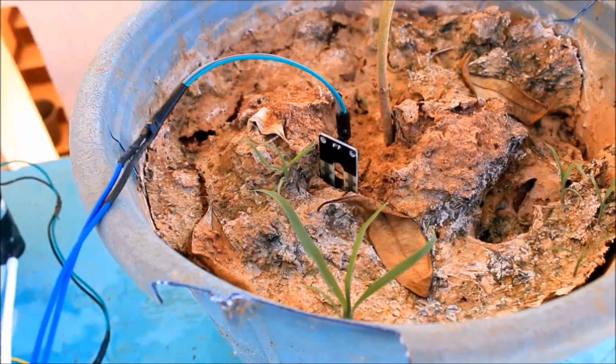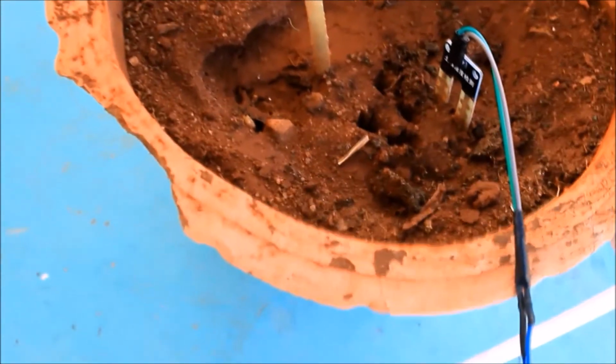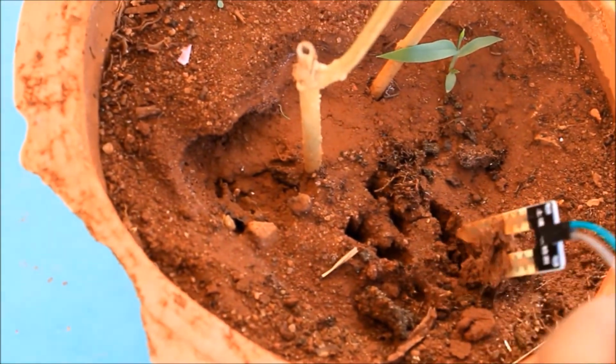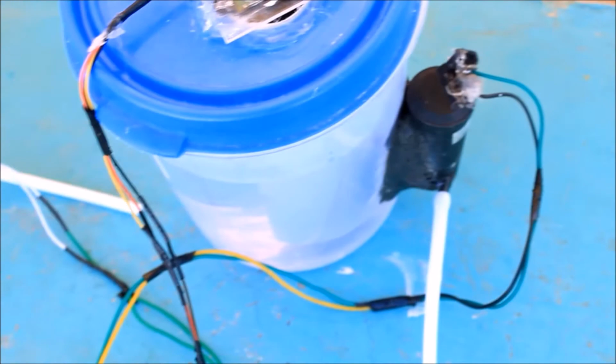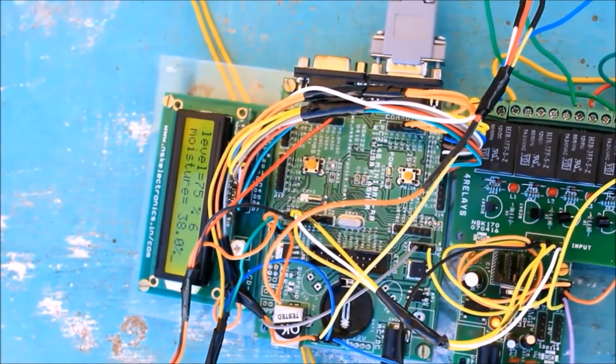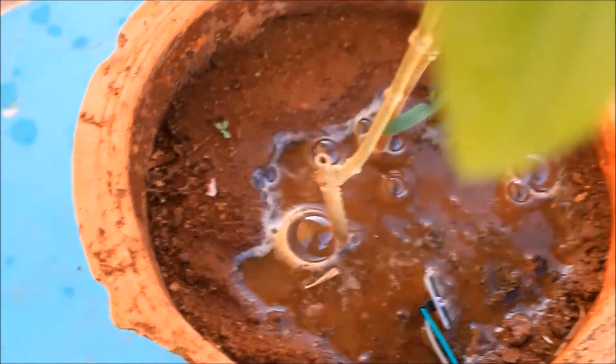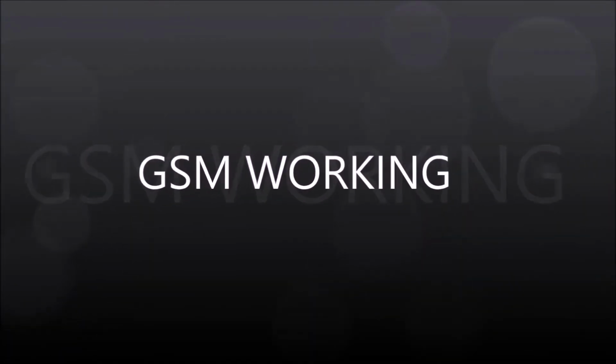The second is the soil moisture test. In the soil moisture test, the soil moisture sensor checks the value of moisture content in the soil against a threshold. Once the value is less than the threshold, it will check the value of the level in the sump. If that is greater than the threshold, then it will turn on the pump to the garden area. Once the moisture reaches its threshold, if it is greater, the pump will turn off.